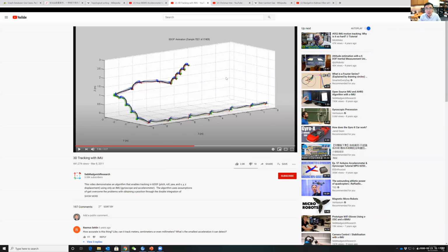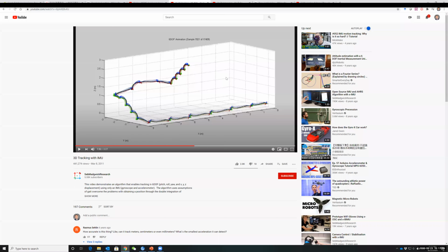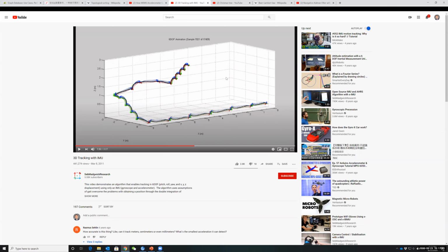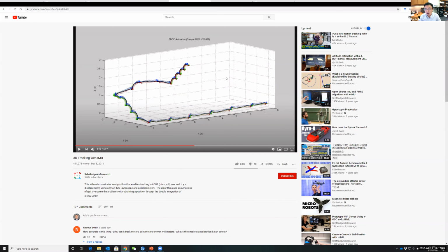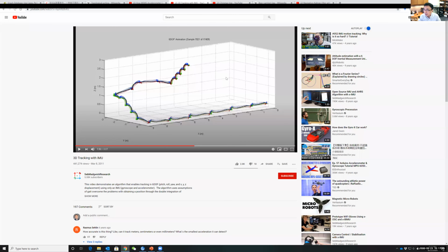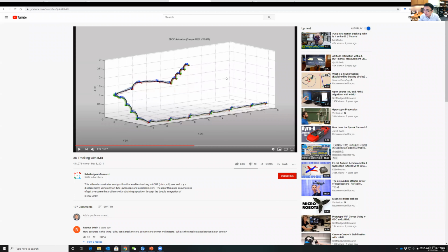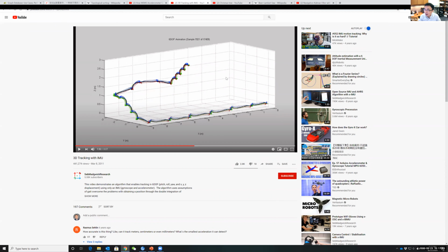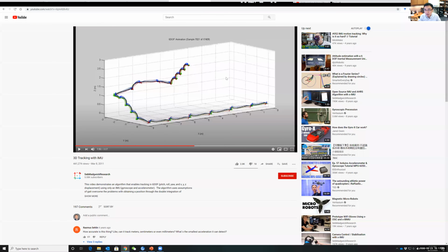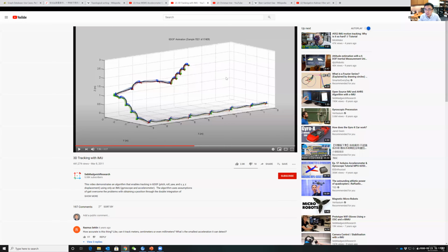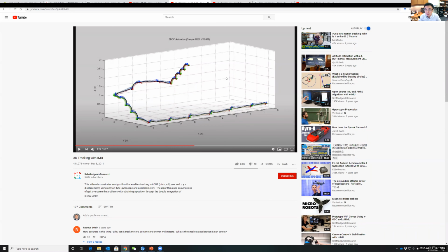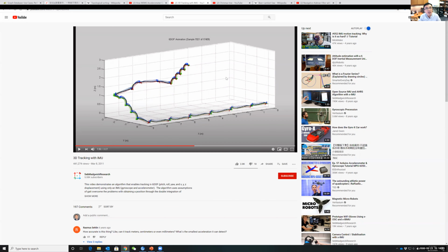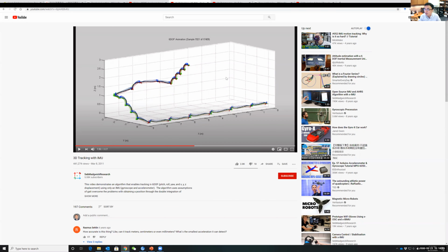To put it simply, we cannot use GPS indoors because GPS relies on the satellite system, and the signal is actually very, very weak. You need at least 3 satellites to triangulate your XYZ. Even outdoors for civil use, the accuracy is, I think the latest one is still within 5 meters. So we are not talking about very accurate.